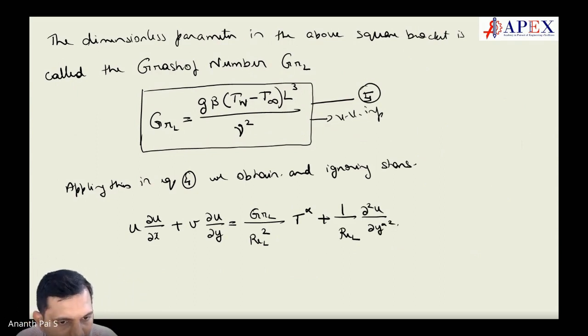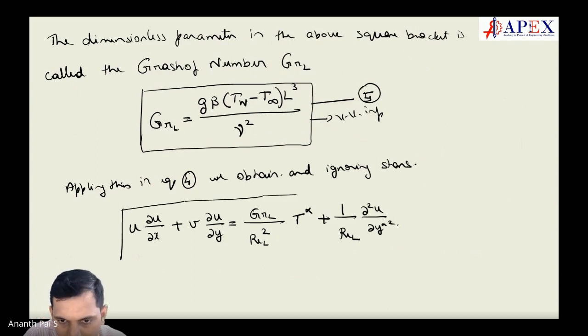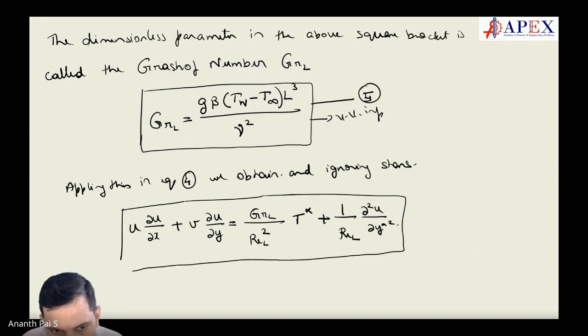Correct. Now this gives an idea, although it is derived for a flat plate, generally it's applicable for a lot of cases. Now when you consider RE_L here, when you differentiate this, see, if Reynolds number is very high, then it almost becomes like a forced convection. When RE_L becomes very high, this goes to 0. So what is this? This is related to the forced convection equation. Does it not make sense?